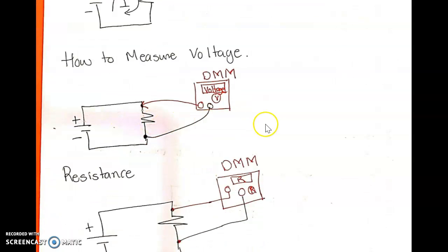How to measure voltage? We have our circuit, a basic circuit. We have a voltage source and we have our resistor. We can only take measurements across electronic elements. We cannot measure between this point and that point because we discussed and agreed that this point and that point would be the same. So if we measure the voltage across that point, the answer is going to be 0. Ideally, we said that we have no losses when we connect components using wires. So we continue with that convention.